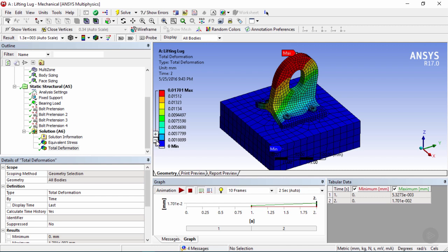So let's say we want to remove this, we can click on the minus sign and now we've removed that color from the legend. We can click on the plus sign and then we get it back again. Now the minimum and maximum values are fixed. However, you can change the other values in between the legend. So let's say you don't want this value to be 0.015, but rather 0.010. You can enter that here by double clicking on it and then pressing enter.